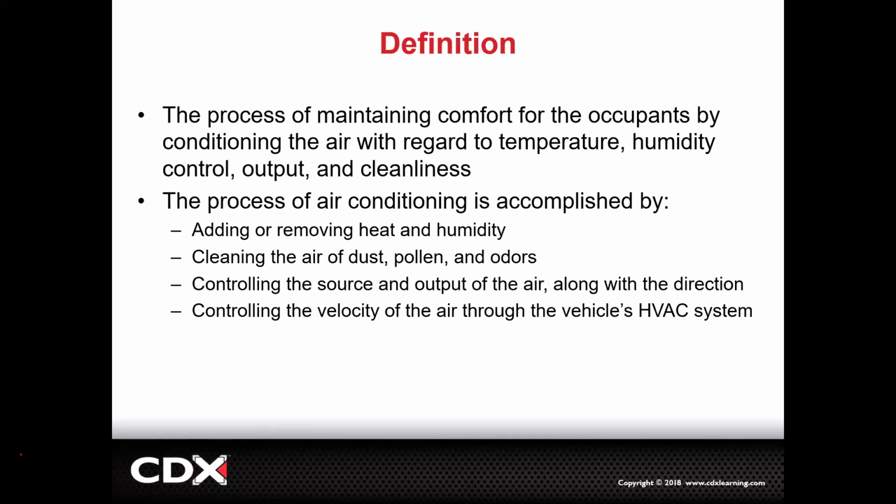How do you remove humidity? You can either heat it, and that'll remove humidity because it'll kind of burn the humidity off the hot heater core. Or, believe it or not, you can run the AC, and that AC will get cold, and the moisture in the air will condense onto the evaporator and drip out the bottom of the car. Both of those remove humidity, so you know.